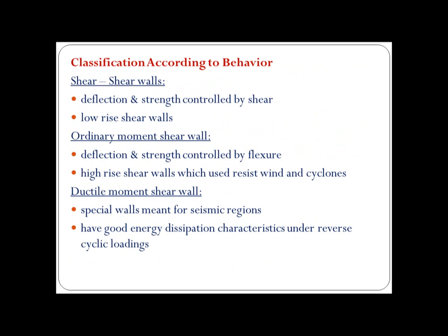Classification according to behavior: simple shear walls. Here deflection and strength are controlled by shear, where shear becomes the major force, resisting the lateral forces by shear development. These can be used in low-rise buildings.